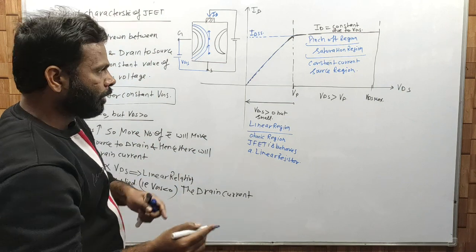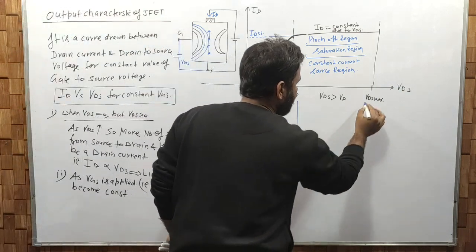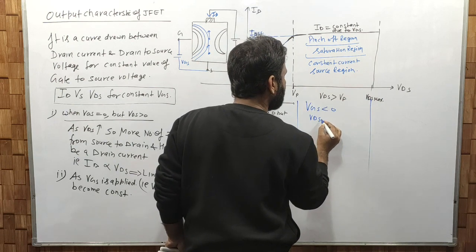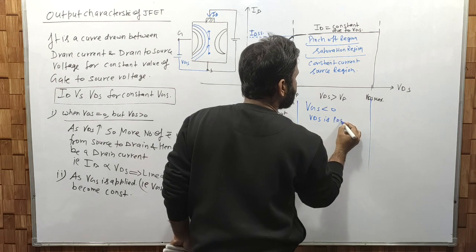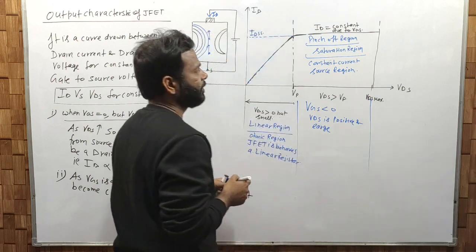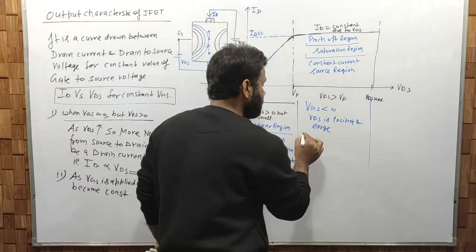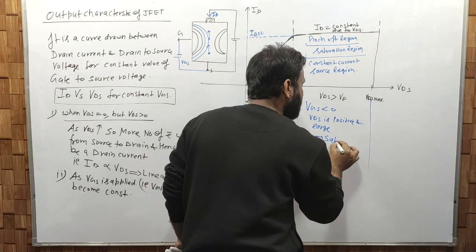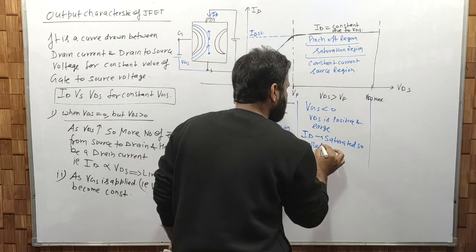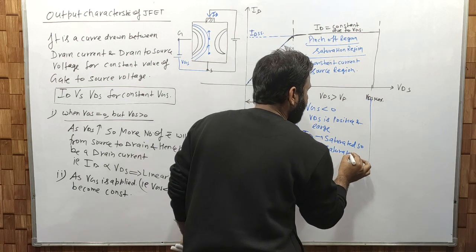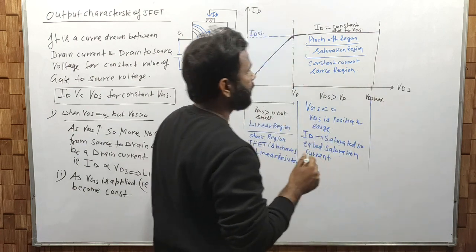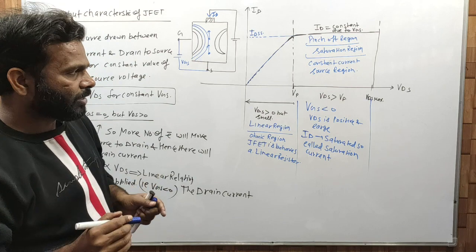यहां तक बात समझ में आ गई होगी। So in this region VGS is less than 0 and VDS is positive and large. Clear? In this region the ID becomes constant. The ID is saturated, so called saturation current, hence the name of the region, the operating region, is called saturation region. क्लियर है यहां तक? आई होप से ये बात समझ में आ गई.